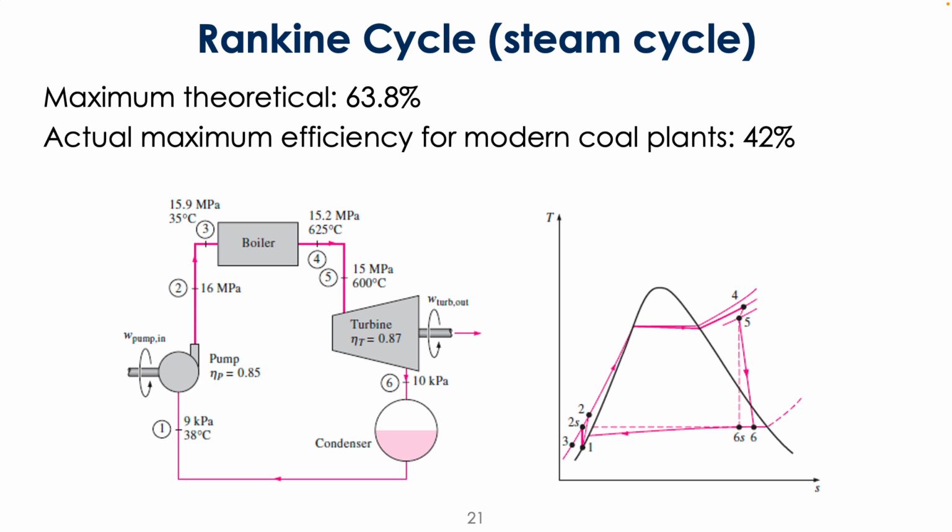And so in this particular case, you have water going into a boiler. That boiler introduces heat and changes the water into high pressure steam. The steam passes through a turbine to extract work, and the energy is translated right into this mechanical energy. And then you have a condenser that takes the steam back into water, right? And we need that stage in order to return back to the pump at the beginning, so that you can go again.